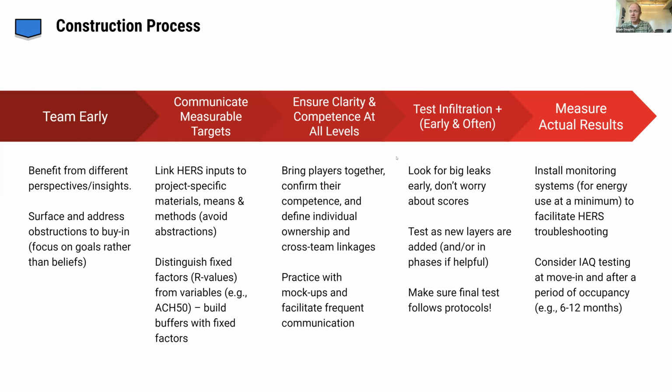One, there's a study, and I believe we have it in the resources at the end, that shows multiple HERS raters working on a single house to see how consistent they are, and seeing a 10-point variation. And some of that variation is, I think, driven by the load that's put on HERS raters. Some of these HERS raters are doing so much volume that they don't have the time to check everything along the way. And I think other things we've experienced are